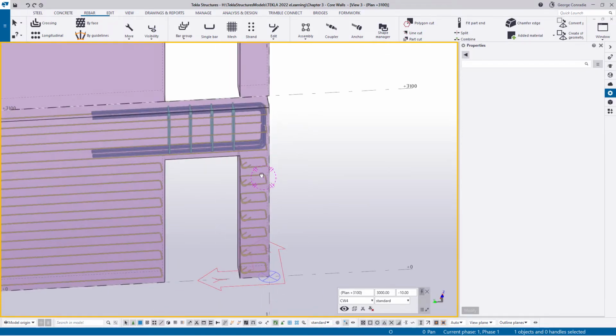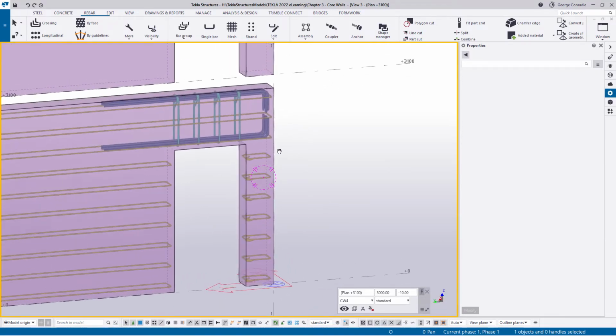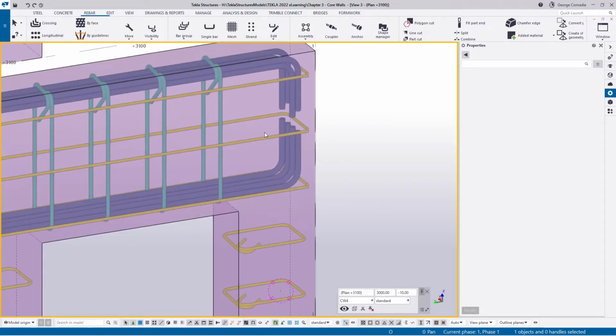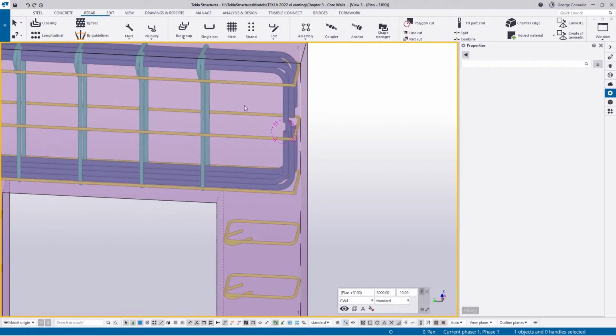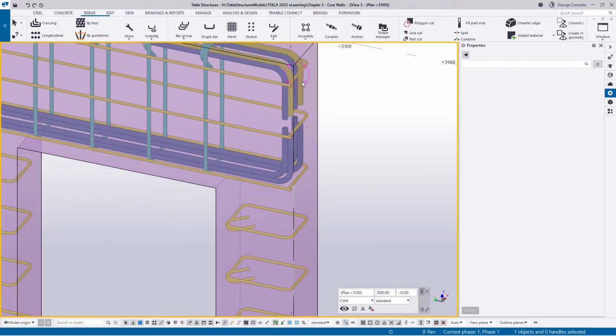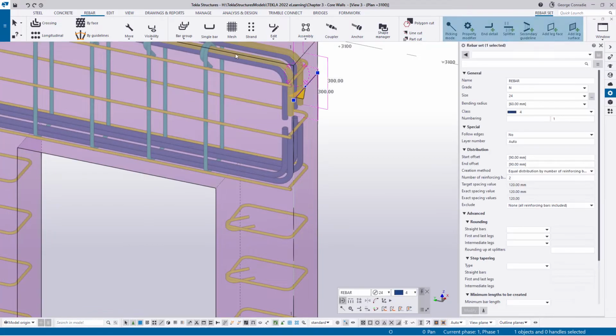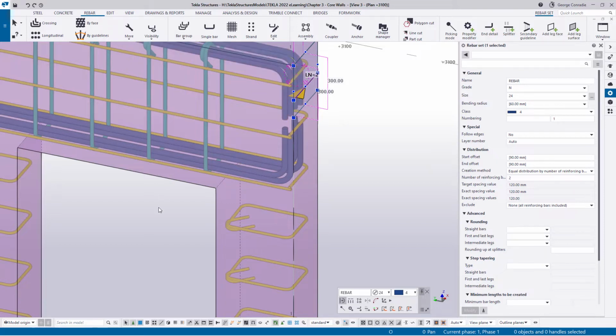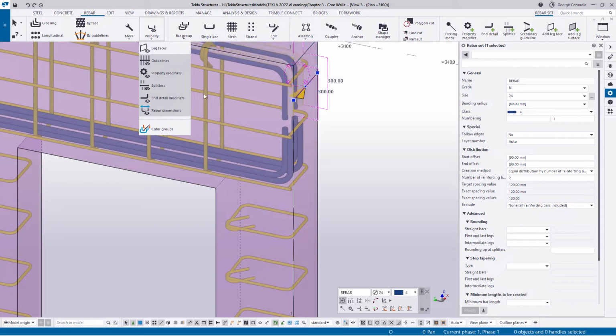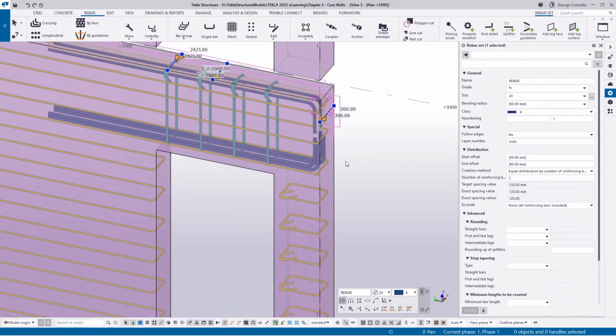Now those have been taken care of and they look pretty good where they are. Now what we can do is click on these, and by the way, because we put this in the outer layer, it's actually wrapped around the outside of those, and these have gone to a different layer. If I click on that, visibility leg faces, that's now become layer 2, and that one has become layer 3, and these are now layer 1. So it's sort of an automated process. It's pretty powerful when it comes to rebar sets, how you can control that.